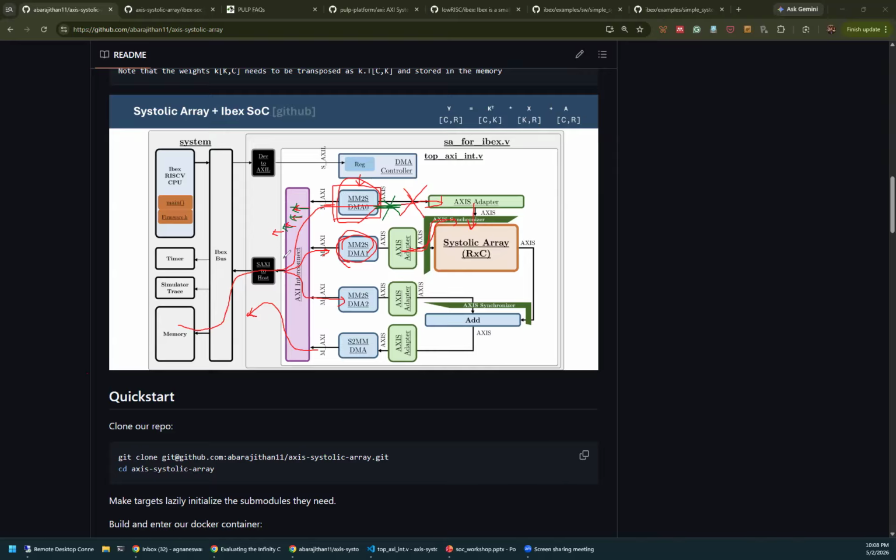So the DMA was being too optimistic. It was thinking, okay, this side might clear up in the future, but I might as well give a bunch of requests, and when the data comes, I can give it. That is how he designed the DMA, he put the logic that way. But then what I found is that now there is a problem.